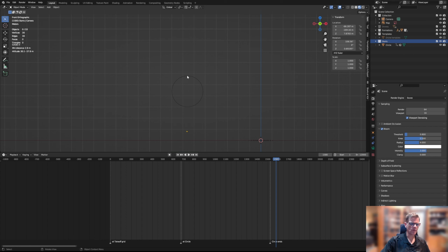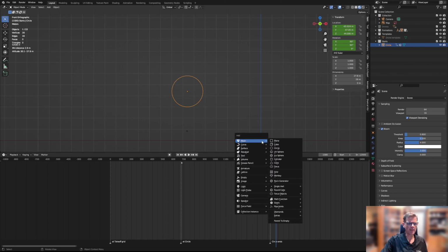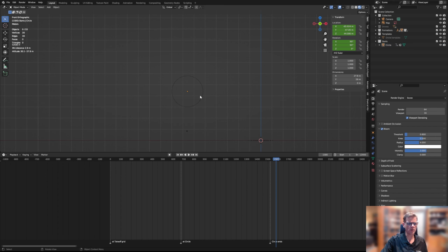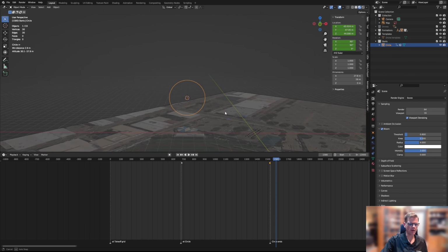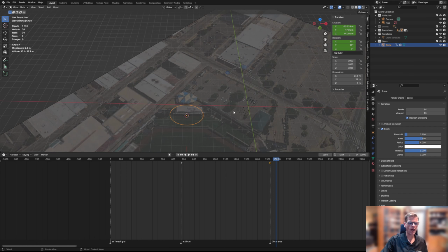And then I'm going to set the origin of this. Well, the origin of this circle is right in the center, but what I'm going to do now is a trick that you'll find increasingly useful as you get more into this: I'm going to move the 3D cursor to the center of this circle. Right now it's at the origin, XYZ. When you hit Shift A and add new objects, it adds them where the 3D cursor is located by default. So if I do Shift S, I get an option to move the cursor to the selected formation, so that now when I add new objects, they actually get added here. Remember, I translated all the way over here, so I don't want things added over here. I want them added where the drones already are.